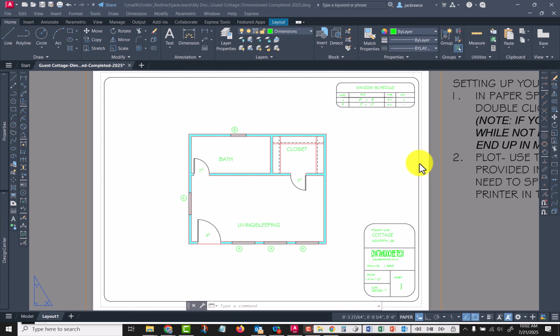In a few of the mechanical drawings, when we're doing a scale other than 1-to-1, or an unusual circumstance, we use annotative style. You only use annotative when you're dimensioning in model space.